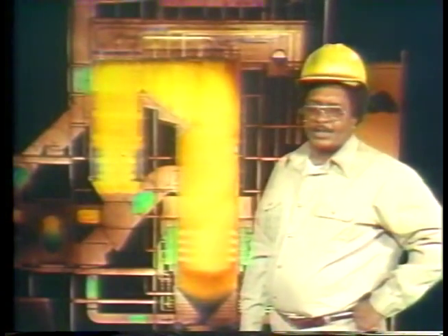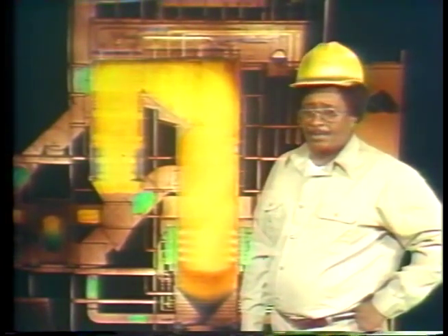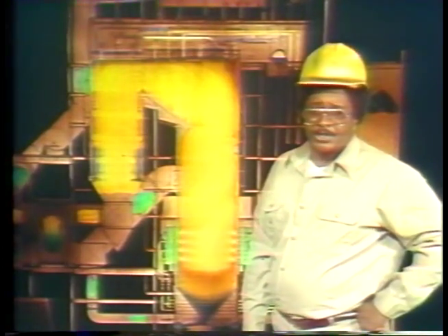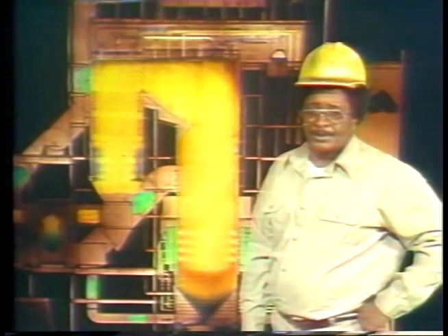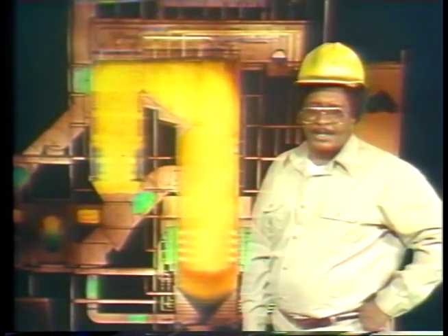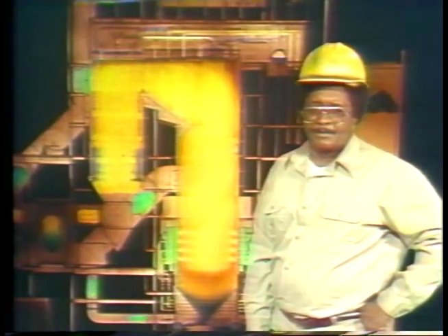You've now had a chance to look at Table 3 and study its organization. Let's look at one more example of how Table 3 can be used to determine enthalpy at a given pressure and temperature. Then we'll go on to look at the conversion factors that are found in some steam tables. The steam at the outlet of a typical reheater is superheated, and it leaves the reheater at around 435 psia at a temperature of around 1,000 degrees.